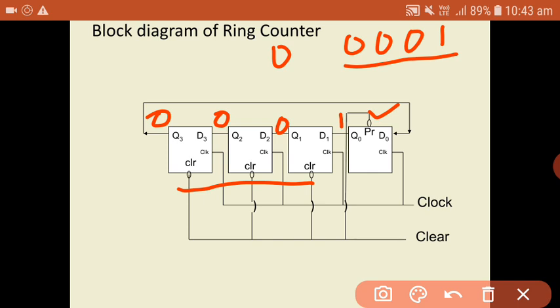So this is the significance of the asynchronous inputs called preset and clear. Irrespective of the clock available to each flip-flop, or irrespective of the inputs available to the flip-flops, if preset and clear are applied, they will be applied accordingly to the circuit.